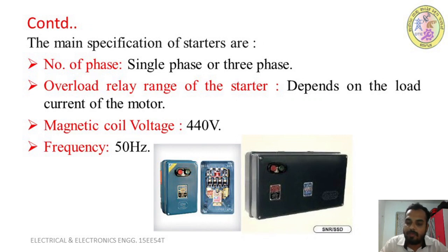So next we have seen energy meter. Either induction type energy meter or electronic type energy meters. Now we are using electronic digital type energy meters. It may be single phase or it may be 3-phase. If the load current exceeds 50 ampere, then we have to use CT along with the energy meter.